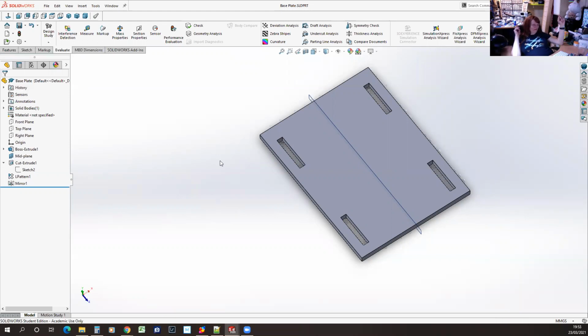The other one is, and this is something that really threw me for a loop when I started with SolidWorks, that if you change the width of this piece to be less than 45, your features following that will explode. They'll all suddenly be marked red, and it's a skill that you'll only learn over time to find out what actually causes the blow up, especially when you don't get the blow up until you rebuild. So rebuild often.